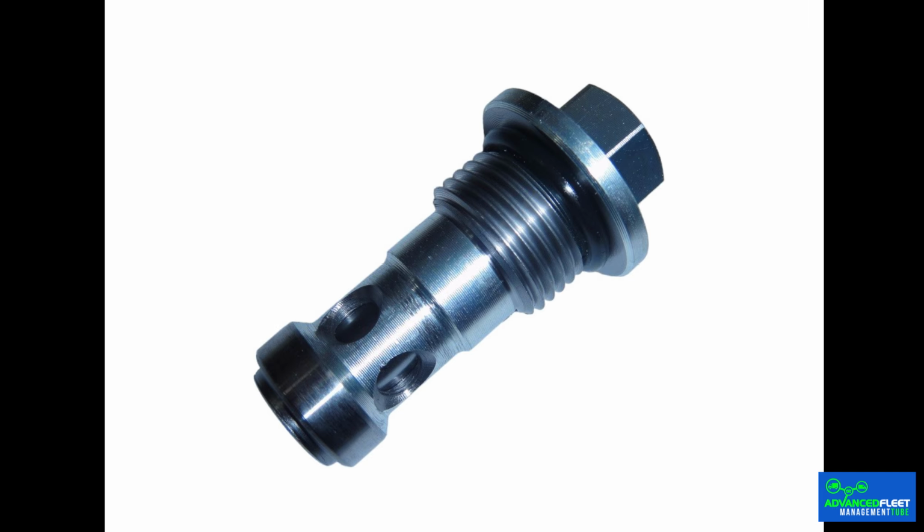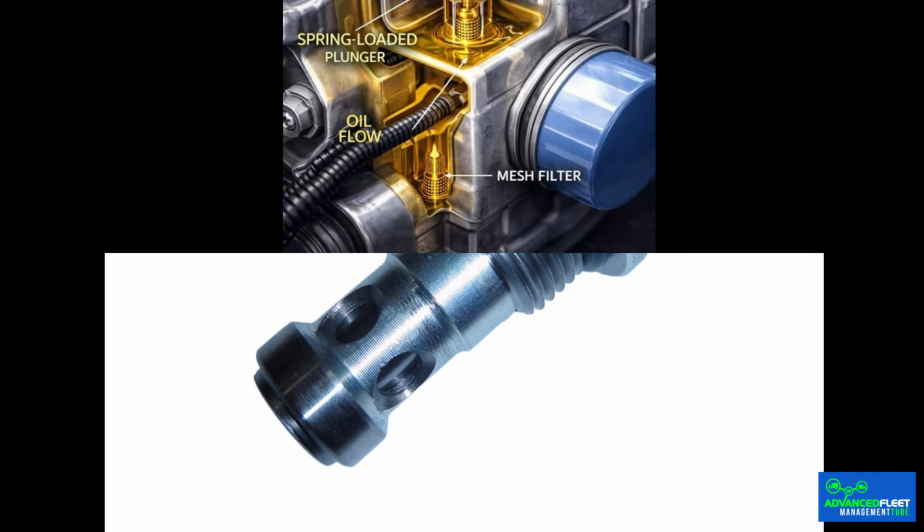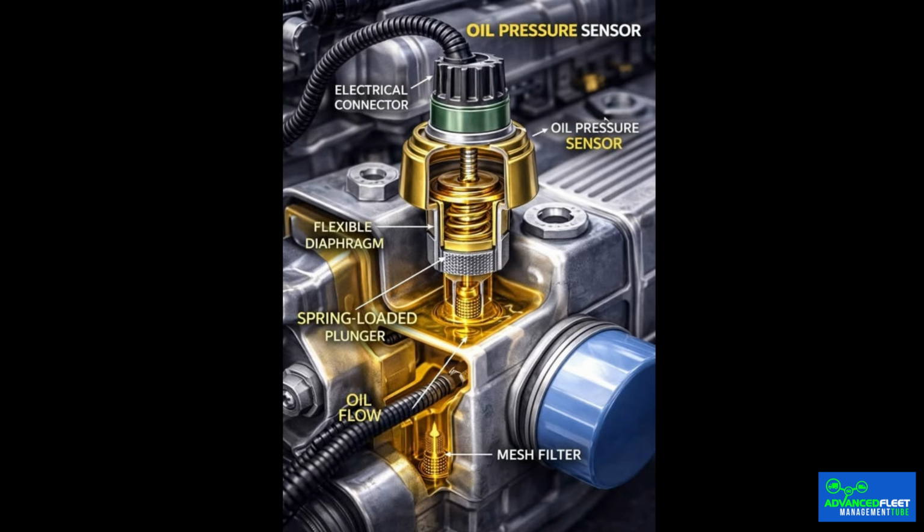Failure of the pressure relief valve. Some pumps are equipped with a relief valve that activates in the event of excessive pressure, allowing for pressure regulation and preventing potential damage. If the valve becomes stuck, this will cause a continuous loss of pressure throughout the entire circuit.